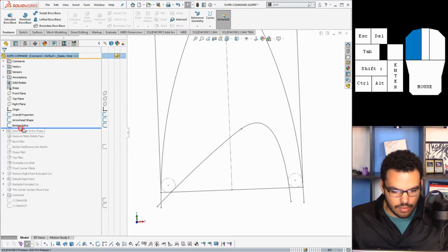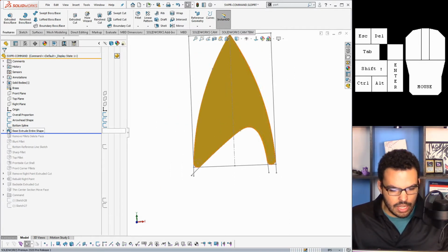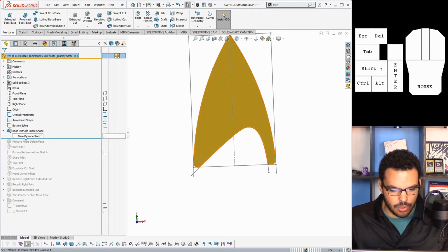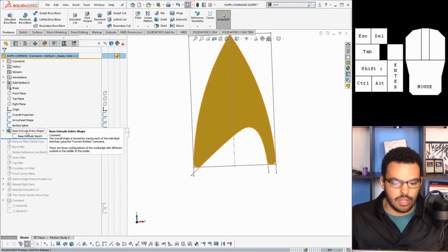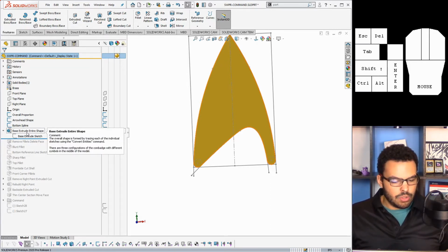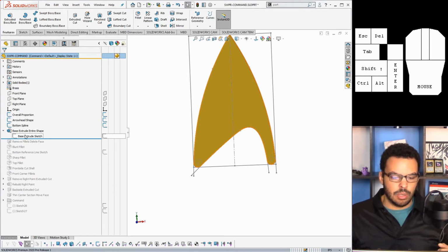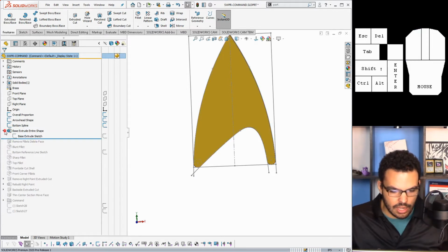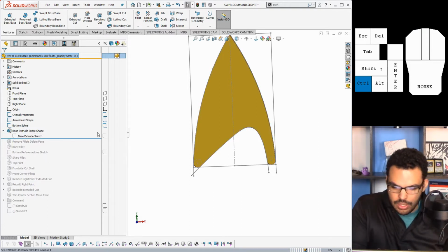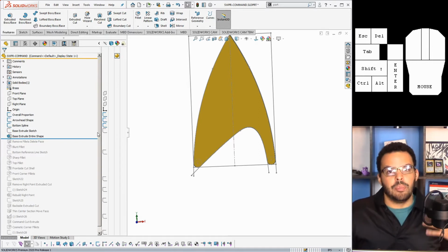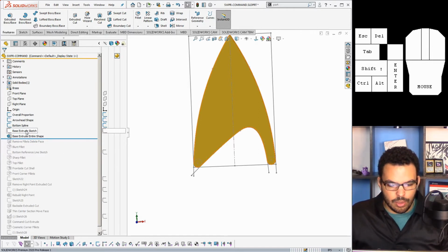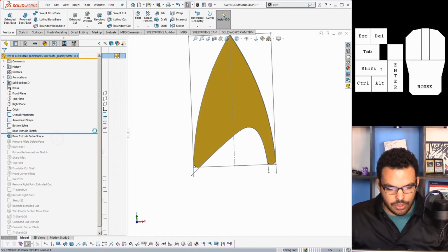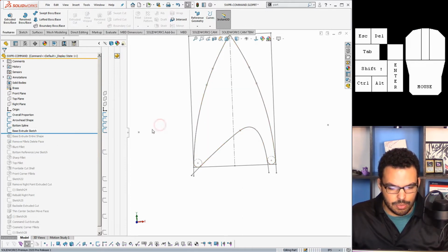And then if I roll this down, all right, so that came all at once. So in fact, I rolled over two items. I rolled over the base extrude sketch and the extrude itself. So in order to prevent that from happening, going two steps at a time whenever a sketch is absorbed, that is, the sketch is just kind of hanging out under here, if I hit Control and T on my keyboard, it'll put everything in exact order. So now I can study the base extrude sketch by itself.